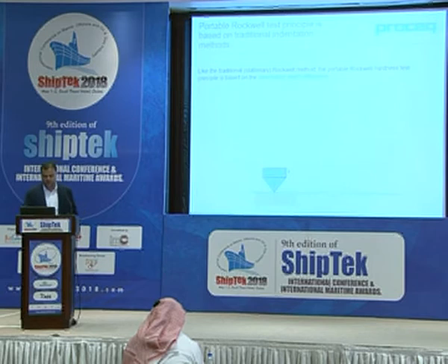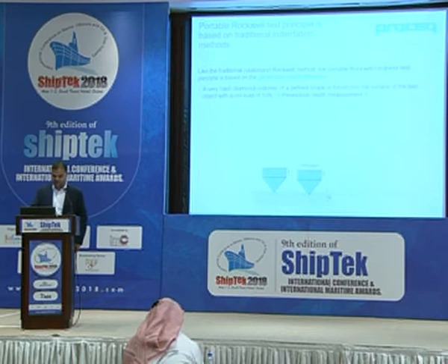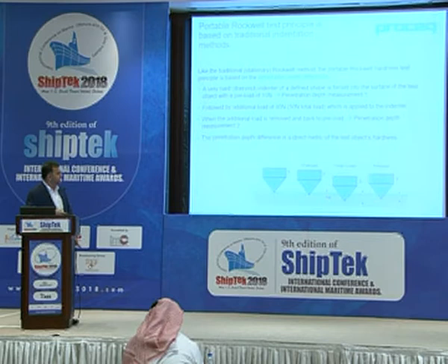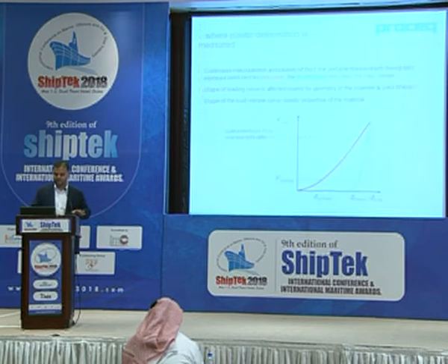If you just have a quick look at the principle of Rockwell testing, this is the same benchtop Rockwell testing principle. Basically, there is a preload of 10 newtons, and then we apply the test load, and the indenter will further deform the sample, and then there is an indentation. Then we release the peak load, and we measure the indentation depth between the peak load and the preload, which is exactly the Rockwell hardness testing principle.